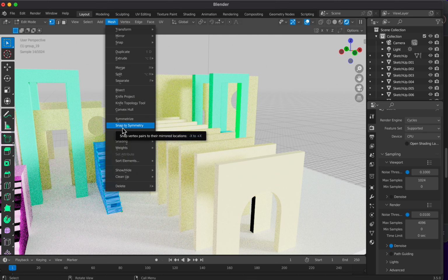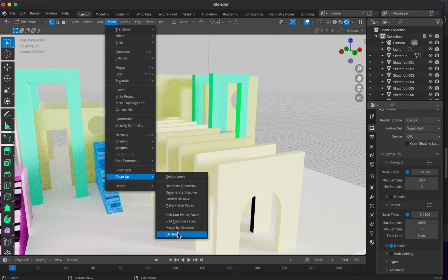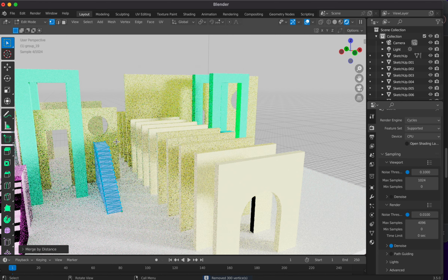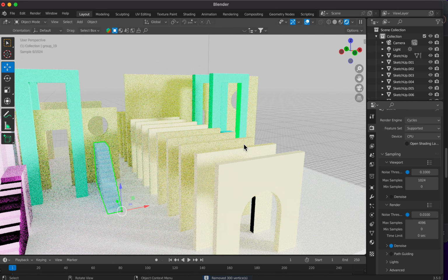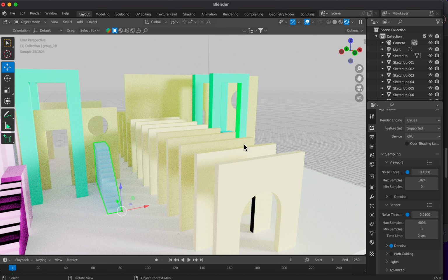But these ray tracing renderers are a little bit slower than something like Eevee, because of the way they've got to do the calculations. I'll just do that while I'm here. If you've got a computer with a ray tracing graphics card, it'll really power through this sort of action, but with the NVIDIA cards, make sure you've got the Studio drivers installed, not just the game drivers.